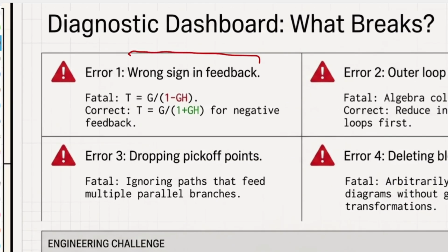If you remember when I told you about the closed loop feedback controller, if your feedback is negative, your final transfer function formula would be, for example, this divided by 1 plus the loop gain. If you forget that and see a negative instead, you think, okay, that is good, it means I can make this one negative, and everything would collapse.